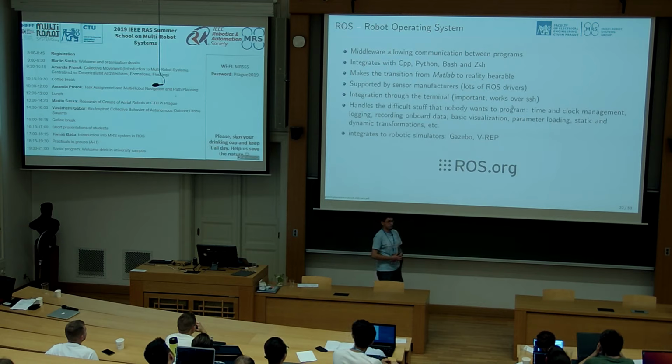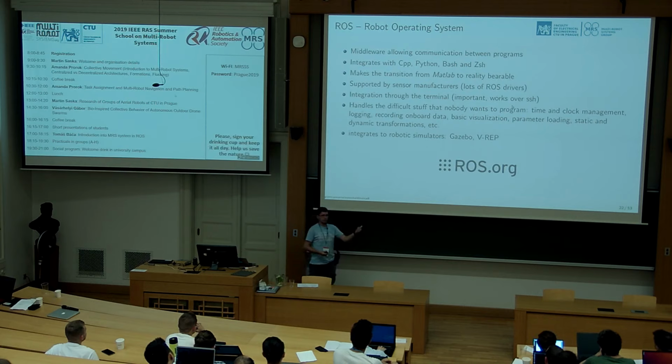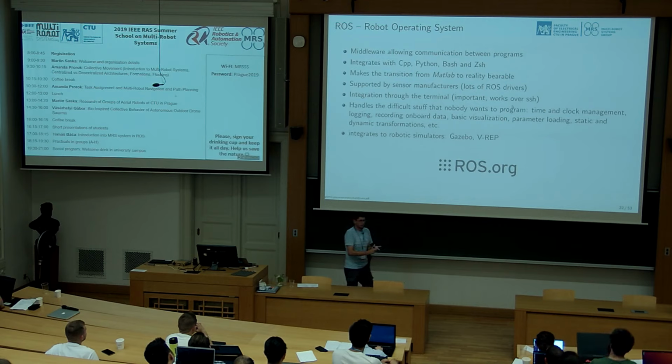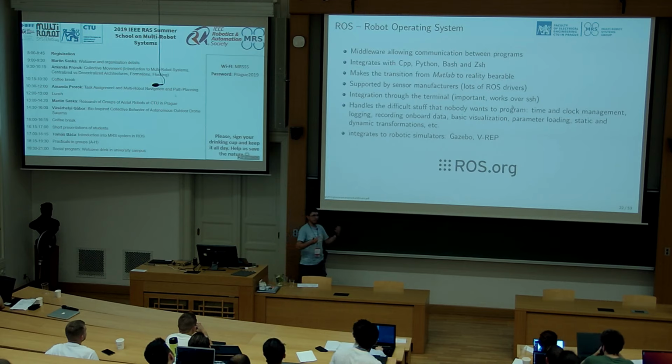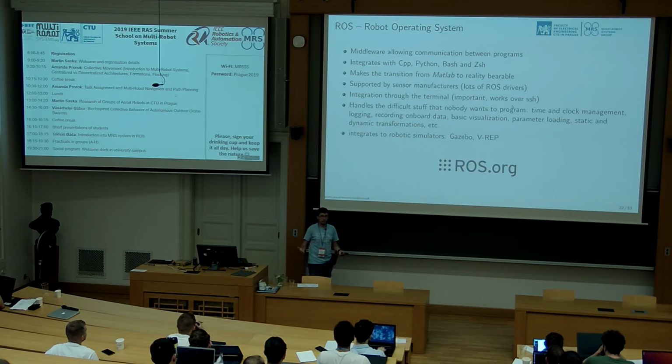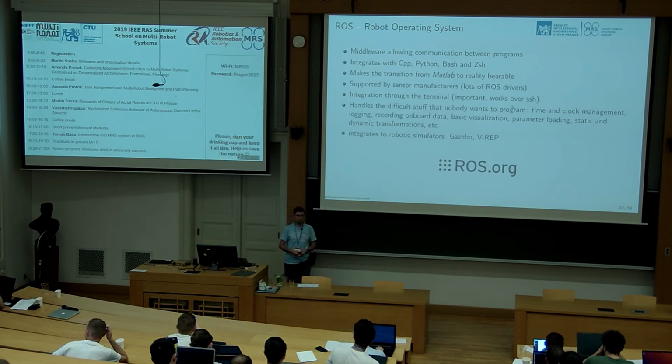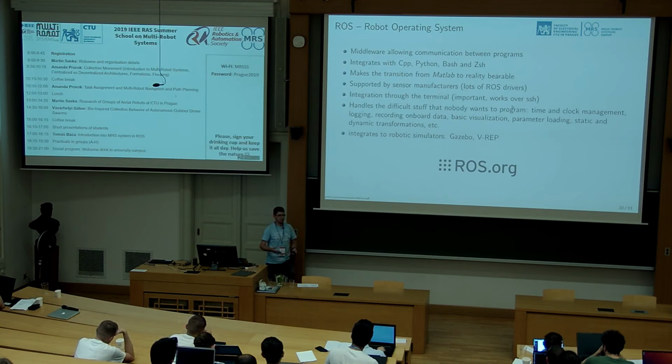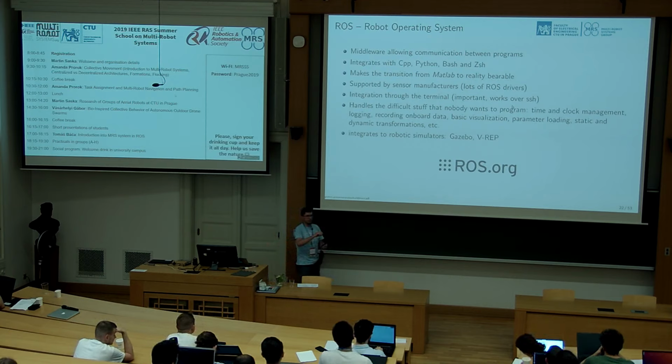And those problematic stuff are those ones which you really don't want to program by yourself. Inter-program communication, time synchronization, asynchronous execution of complicated pieces of code which might not even be related, like computer vision and control. Those really run on different math problems. ROS can help you with lots of sensor integration. Nowadays, manufacturers produce drivers which are directly developed for ROS. So basically, you buy a sensor and you go to the manufacturer's web page, and there is a link to download the ROS driver.